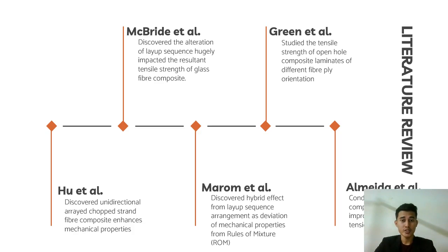The investigation of glass fiber yielded unidirectional glass fiber exhibiting the stiffest behavior compared to other layup configurations, which only elongates about 2.46% strain when applied with 474 megapascal tensile force, while steel fiber composite laminate yields about 4.5% strain at only 161 megapascal.